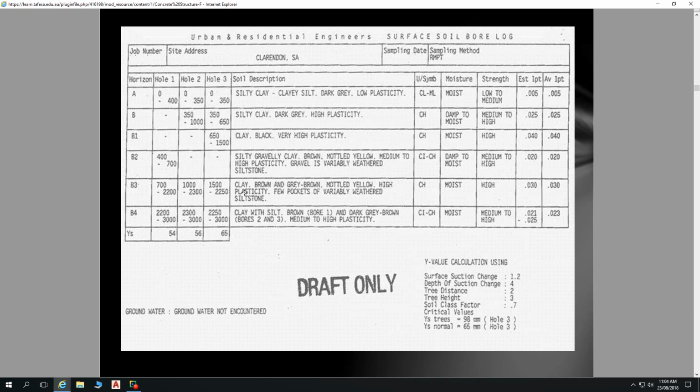So if I was to do a visual interpretation of that, let's say some land sloping like this, and then we've got B3, B4. So that first borehole is taken through this. And then we've got our topsoil happening. So this is our humus layer up here, that's horizon A. We've got 400 mil of that. But then we don't have any B1 and B2. We've got B3 and B4, and then we're at 3 meters down here.